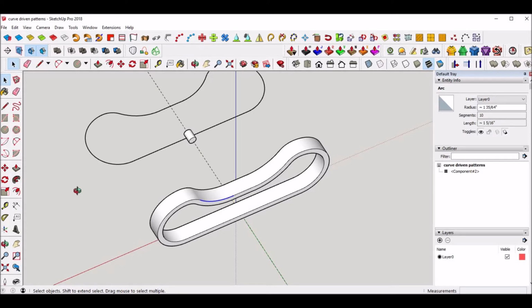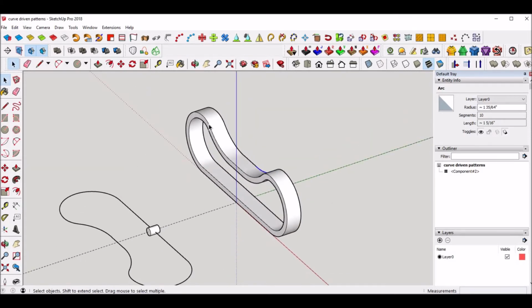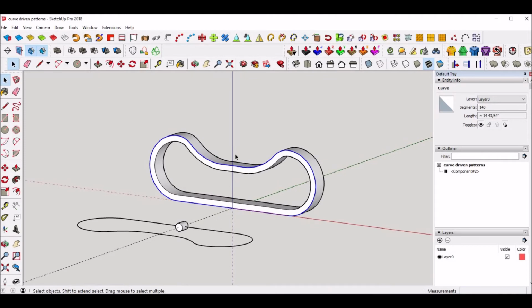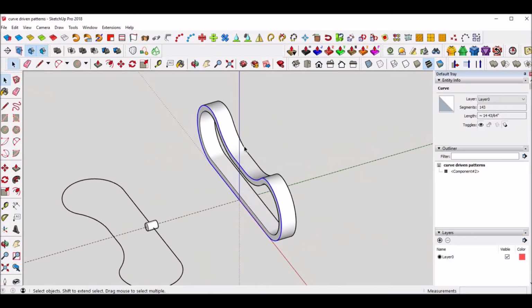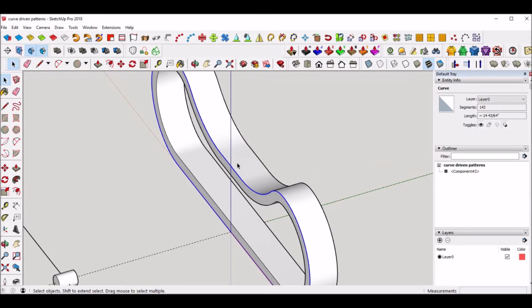Anyway, so what I did was I went ahead and I welded this entire front line together. Now, I know this is 1/2 an inch wide, so my midpoint is 1/4 inch. Now, you could put a little guide right here, 1/4 inch in off the blue axis, so that when we move this one, rotate it and move it to the center, it'll snap.